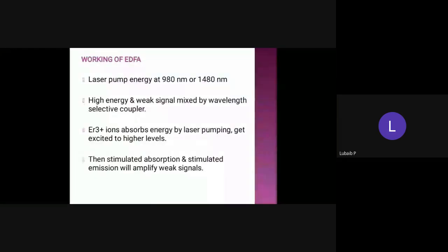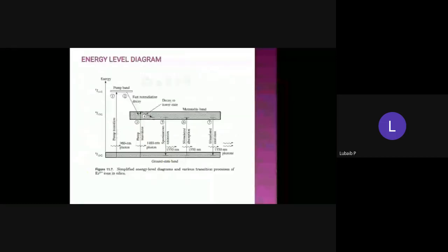This excitation leads to population inversion, and the stimulated absorption and emission then amplify the weak signal. That is the basic principle behind the working of the EDFA.